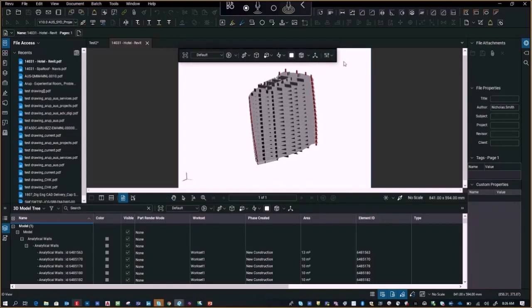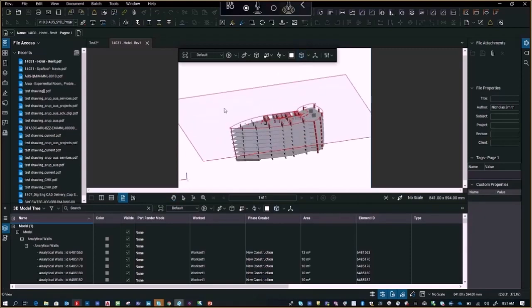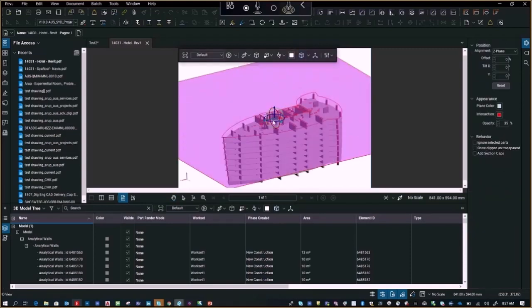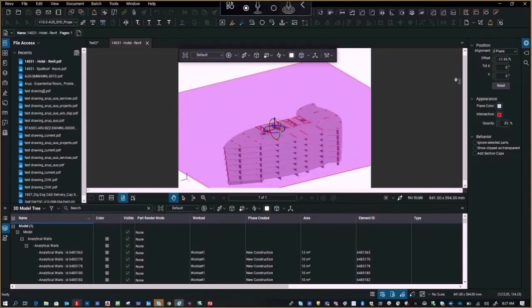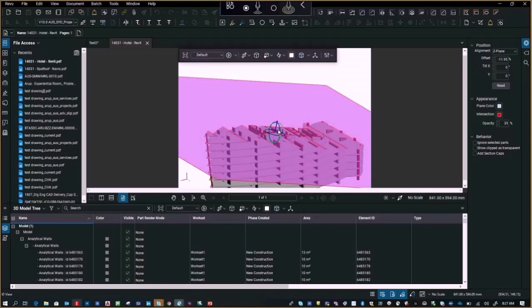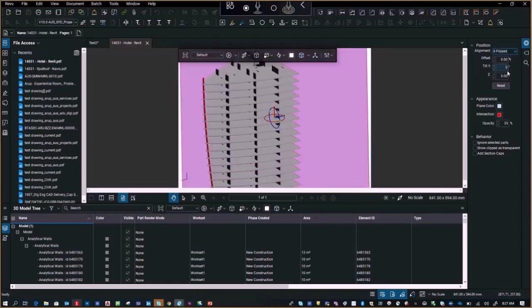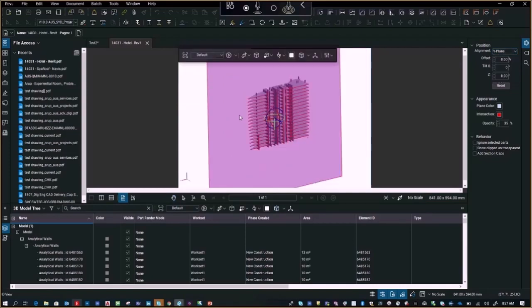So there's a ton of different options, like rendering options, lighting options, but you've got your sectioning tool, similar to the Navis tool. You can click on your sectioning tool and move it up and down. Then over on your left, see the alignment, the Z plane. Instead of using this transform box, you can rotate the planes manually, but it's got all the default ones: your X, the other side of X, and the Y plane.